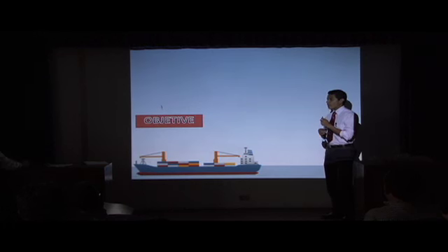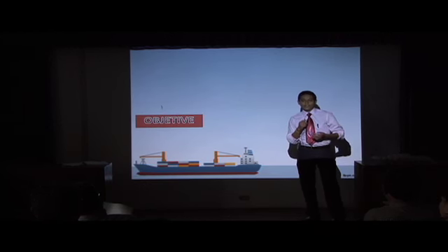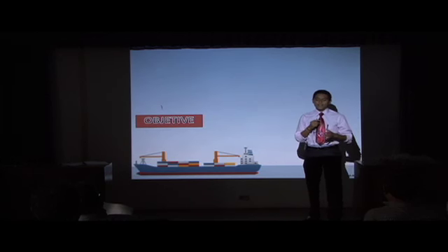And why do we calculate the first 4 frequencies of our system? Because when the excitation frequency is equal to the frequency of the system, resonance occurs, and this resonance is very dangerous for our system. It can fracture a section of our shaft.